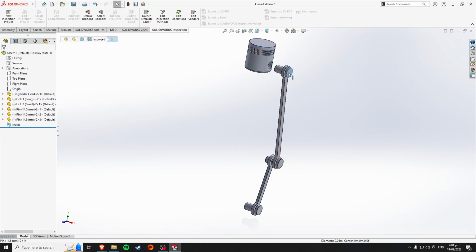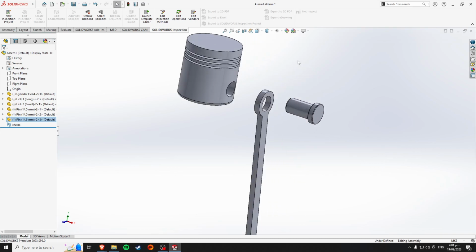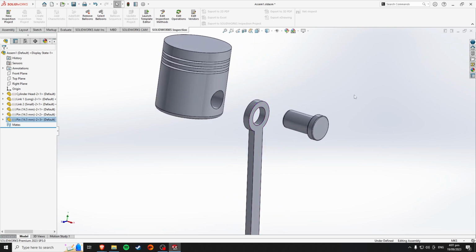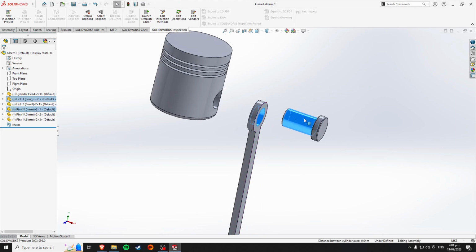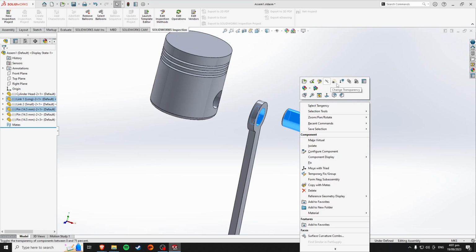Now, the first thing we're going to do is make the individual components. Since the bolts were fixed when saved, the first step is to unfix them so we have space to work. Next, connect the cylinder assembly to the link. Focus on the bolt and the inner wall of the link, select it, then shift-click the wall of our bolt. That is what we mate first.